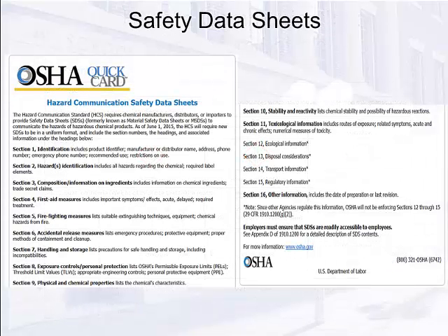A safety data sheet must be maintained for each hazardous chemical used or stored. Employees must have access to the SDS at all times. Exceptions include the use of consumer products when the product is used as intended by the manufacturers. For example, an SDS is not required for Windex as long as it is used for cleaning windows. However, if Windex is used for cleaning some processing equipment, an SDS must be maintained.